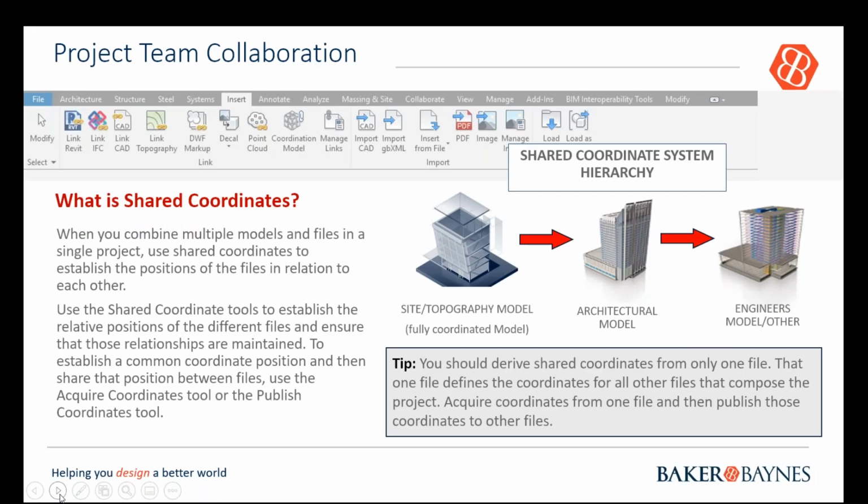So first, the external. This is with your project collaboration team. And that means if you're in the architectural space, it would mean your engineers and your architects and maybe your surveyors, whoever is working in Revit. You have the ability to now link in Revit models into your own Revit model if you have one, via a couple of processes, by linking in Revit or IFC files. Hopefully it's Revit, not IFC files. Then it's a little bit more intelligent. And usually we suggest using a shared coordinate system to help link in that information a little bit more intelligently.